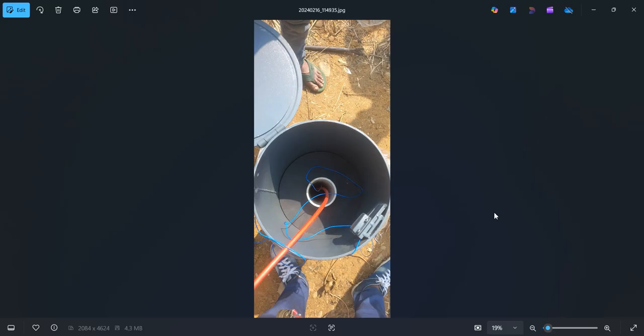So in the particular case of installations, there are a few considerations to be taken. Firstly, we need to know about the purpose. Are we going to install this for a longer monitoring, or do we want it for a shorter time? If you are going for a long monitoring, you don't have to do the casing for the sensor. But if you are going for a shorter one, you need to definitely make sure that it is not permanently fixed inside. And this is a permanent installation in which we have added the cement also, to make sure it won't be subjected to some theft or robbery.